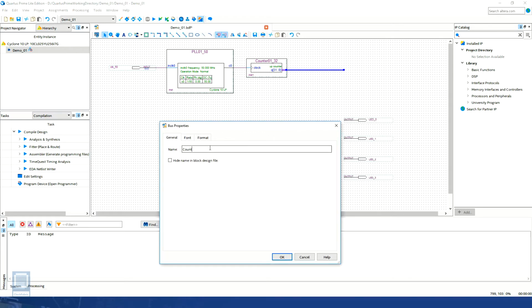This step involves a quirky little trick here to give this bus a proper name. So a bus, by its nature, has an array of elements, which can be represented in HDL by using this square bracket notation as shown on the screen. This notation also shows how we want our bits to be arranged. So if we had it set like 0 to 31, then the bits would be arranged in reverse. For now, let's just set it as 31 to 0.